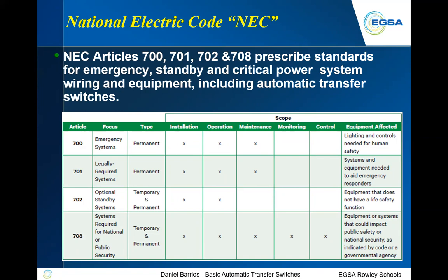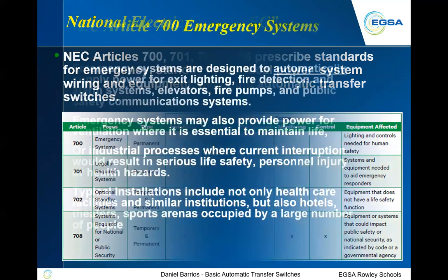These are critical operation centers, and that's your 911 call centers, your fire dispatch or such. Those have now been added, so you must have emergency power. Again, though, even if you have an office building, if you have all of your accounting, your data center or such, which you would require to keep your business going, even under optional standby, you can have power.